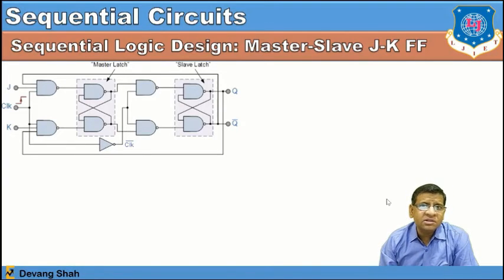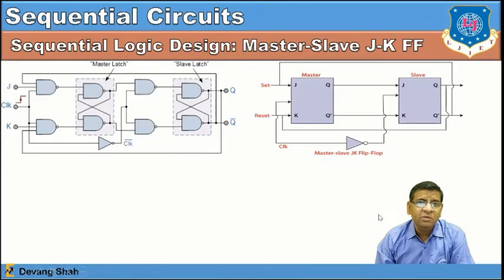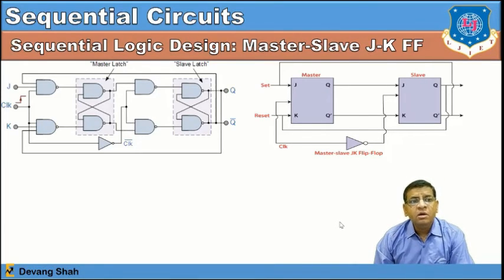By that way you almost overcome the race around condition. Race around condition is like somebody is waiting, and if both are running at the same time, they are never going to meet. So this is called the race around condition. In between master and slave, we have to generate a specific time delay such that this race around condition can be removed, right?